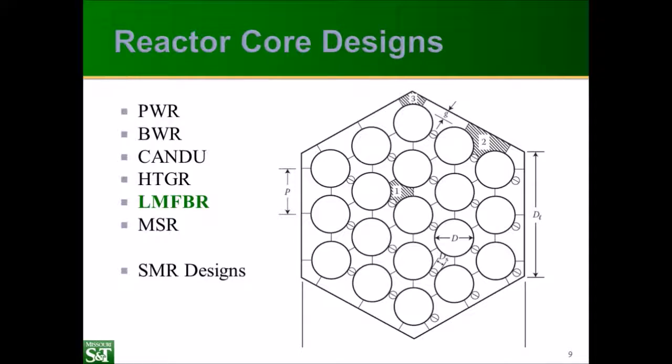So then, for this system, you would have to transfer the heat from the liquid metal to some secondary coolant to generate power, usually steam. For this reason, sodium-cooled reactors tend to use 3 loops to avoid the possibility of a sodium-water reaction damaging the primary system in case of a steam generator tube rupture.